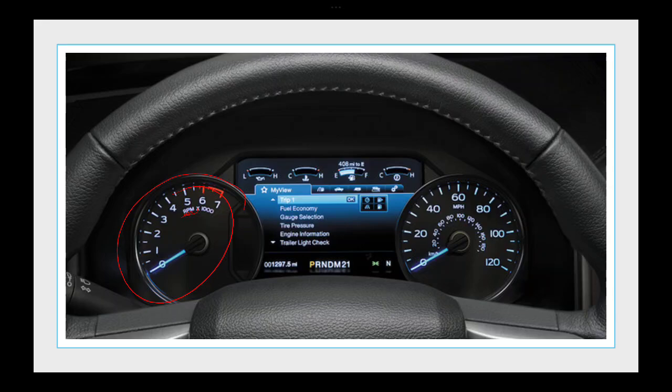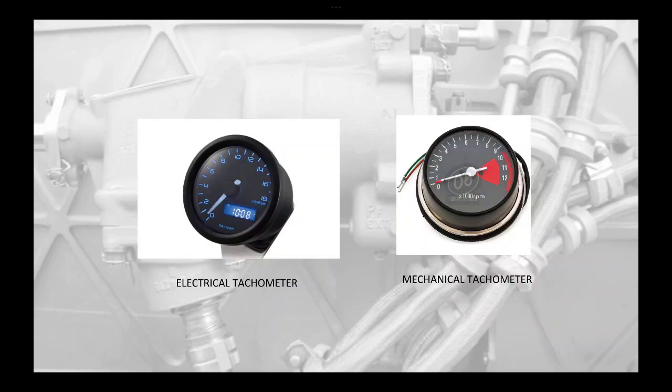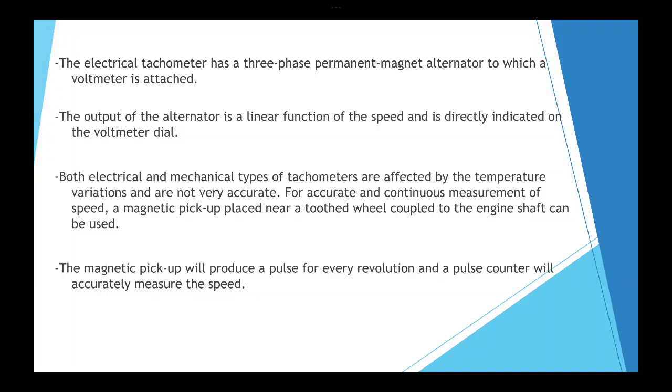Okay, here's an example of your electrical tachometer and a mechanical tachometer. Let's move with the electrical tachometer. The electrical tachometer has a three-phase permanent magnet alternator to which a voltmeter is attached. The output of the alternator is a linear function of speed and is directly indicated on a voltmeter dial.